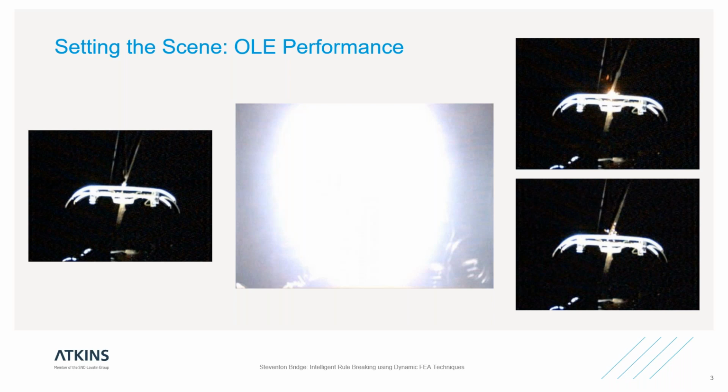Now, the wire has to be tensioned to provide good performance, so we apply anywhere between 1 and 2 metric tons of tension depending on the system. And broadly speaking, the faster you want to go, the higher the tension needs to be. I'll show you an animation in a minute which hopefully makes that a bit clearer. Meanwhile, the pantograph itself has to be very lightweight in order to have low inertia, and you need low inertia to be able to follow the variations in the wire position. So the pantograph has 2 levels of suspension to deal with that. It has primary and secondary suspension to deal with both low frequency and high frequency movement in the wire, and I've got some video that will illustrate that shortly.